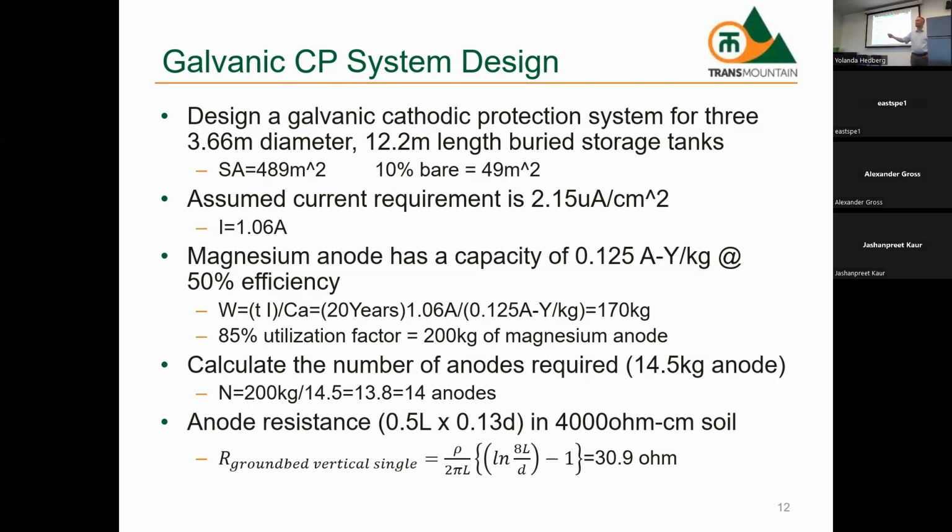Maybe someone just put some, I think it was coal tar, they just slapped some goo on it. It's old, it's sitting in the ground, and it helps us to design a system better than 0.0001% there. But that's the fusion bonded epoxies of right now. That's how good they are. I'm going to say like 2005 maybe, anything prior to 2005 is like 5 times worse than that. And then the 1990s, we're talking like 20 times worse than that.